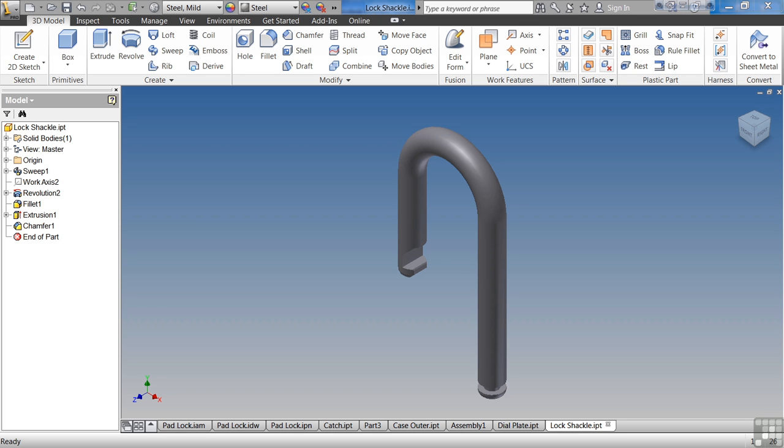You wouldn't start out by creating the notches or ribs in the bottom of it, fillets or anything like that. We create the overall shape. Whenever we determine that shape, we decide that that's a critical aspect of that part. So that makes it go in order of importance, being the first thing that we create. So let's try to create a sample model just to give us something to work with.